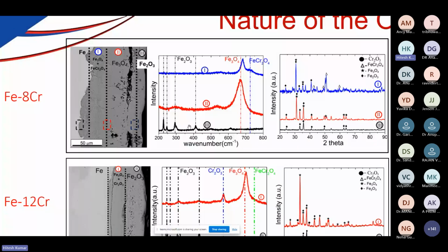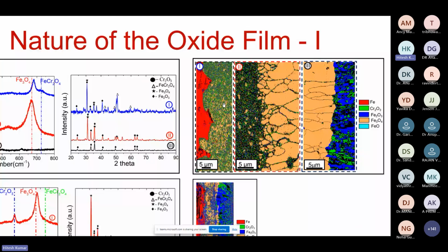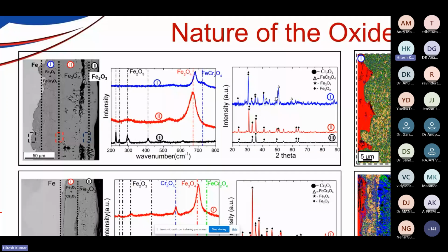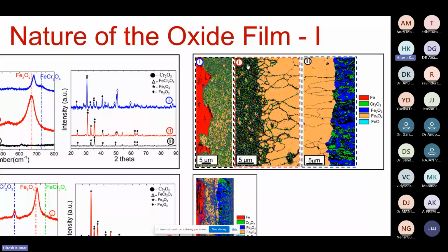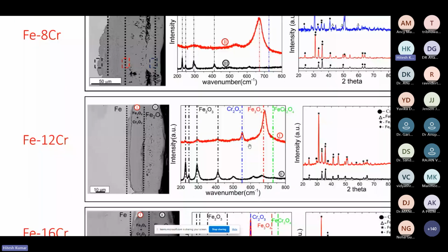This is also confirmed with the help of X-ray. To confirm this, we also did EBSD analysis. Because it's a big oxide layer, around 100 micron, we divided it into three different regions. And you can see how the columnar growths are taking place, one big single grain in the columnar. This happens during solidification. The solidification concepts will be there to confirm these things.